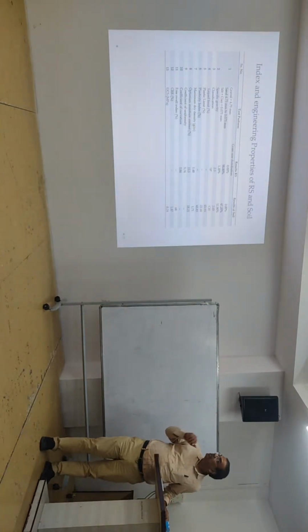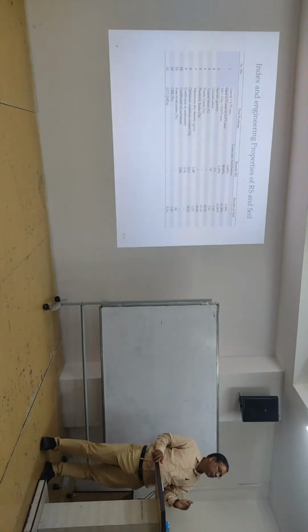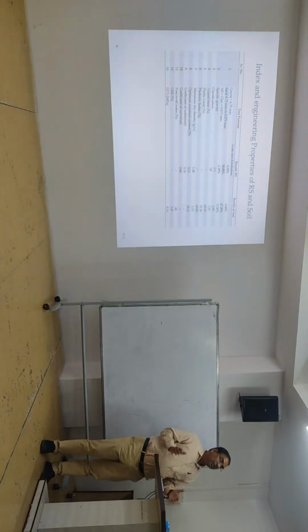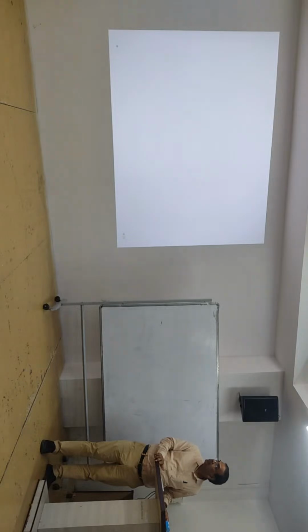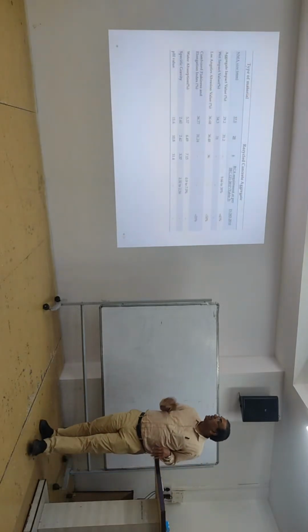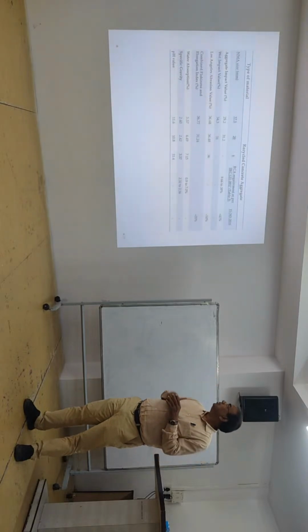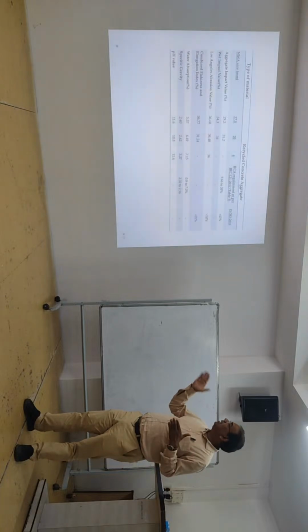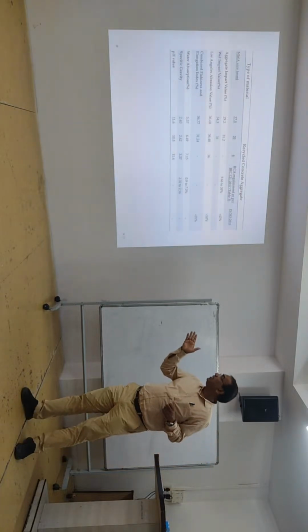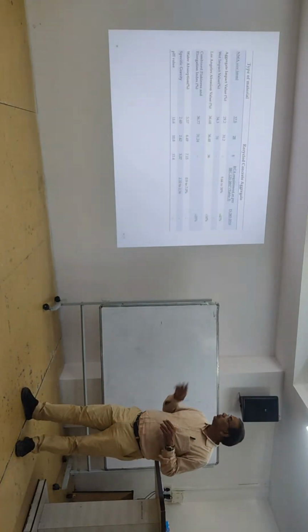And what is 2%? 2% is only something silt and clay, that soil that we get during the bringing of that material from the different location to the site. So recycled aggregate, I can see that different aggregate properties are also good, not so bad, so that you can use for a different layer. So pH value also you can see is good. Specific gravity of the materials is also good.